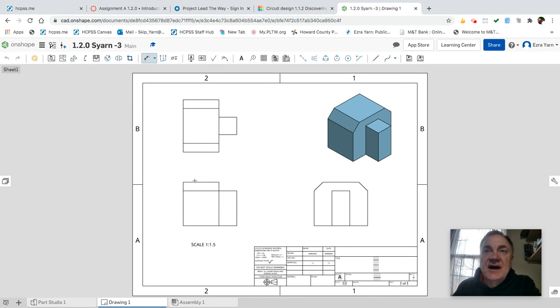We'll click on the dimension sign and we'll add dimensions. I click on this line and go straight up. I go from here to the outer edge and go straight up. So I'm going to center the dimension between the dimension line. So I have all of my widths, width from here and my width from here. So I have the two widths that I need.